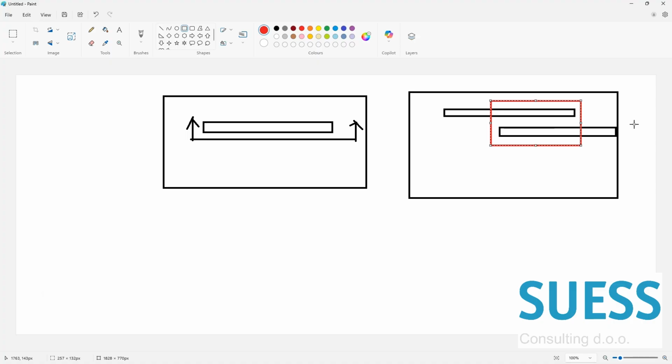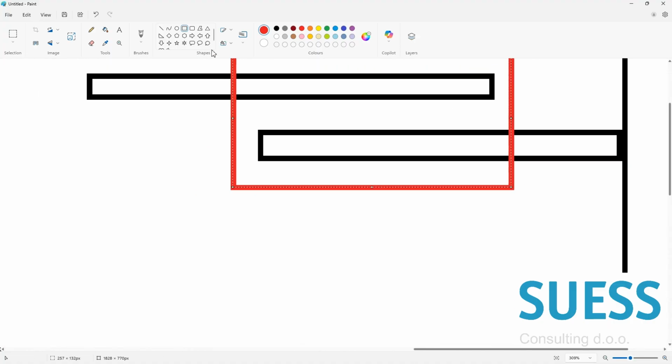What is also good that I explain over here: I'm not looking at the vertical distance from center to center. I'm actually calculating the top to bottom, let's say, effective distance. And if you typed that you want to check if the cable trays are closer than 150, and if this is 130, then the script will collect those elements and it will inform you at the end of the calculation.